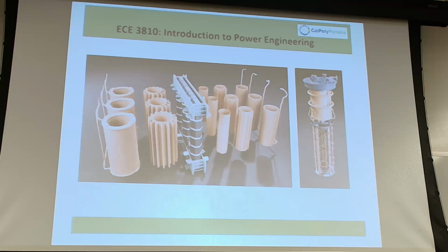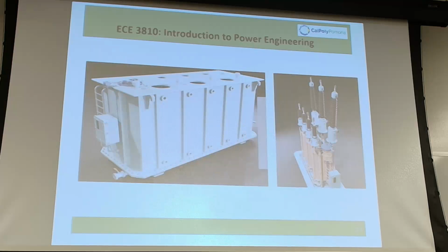When you do the lightning impulse, those little bubbles show up on the test. So they had to take the oil out, take all the light parts out, and dry them up again. It was a big deal. That's what I'm trying to tell you, that it is a very, very meticulous process, and companies can lose millions of dollars.